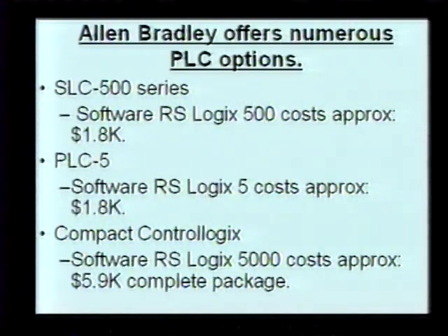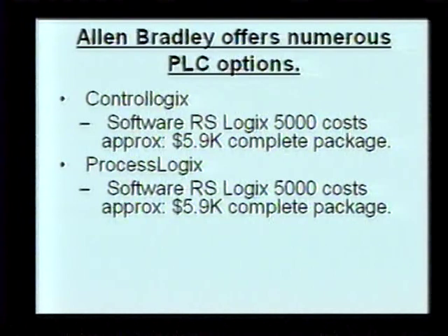Once you understand how to program the RSLogix 500, it's not a big jump to go to the 5 or the 5000. You'll understand it's all laid out about the same. There are just slightly different things about it. But that's the nice thing, once you do understand the 500, you can jump to the 5 or the 5000 relatively easily. The ControlLogix is about the size of an SLC 500 system. It has a tremendous amount of communication options, and it does require the RSLogix 5000 software.